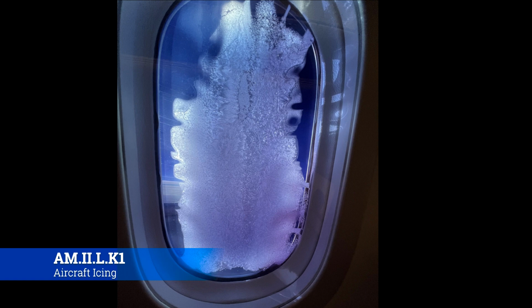And then you go and do a BIT check on it on the ground, and it passes. Then you do a maintenance operational check, so you actually try to use the system, and it works just fine. So you say, well, I could not duplicate, and you sign it off. Well, the pilot comes back, gets in the same airplane, and is super mad because he's having the same problem again, and he already wrote it up two or three times, and you keep saying you cannot duplicate.